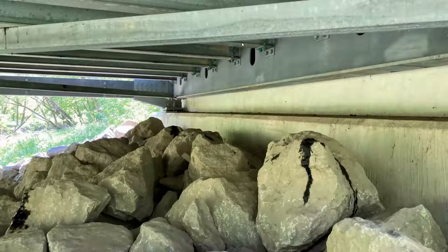Here's the end of the bridge, the abutment view. You can see the truss bearing, shoe and pad, and then also an end floor beam, which picks up the last panel of stringers. The access holes that you see there provide for an erector to get tools behind there to finish tightening the stringer clips. There's no step up for separate stringers. It's just one constant seat across there.